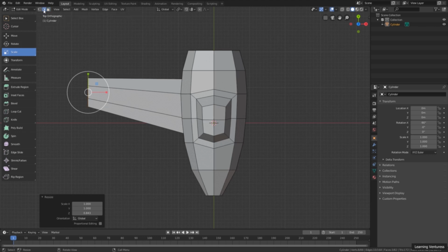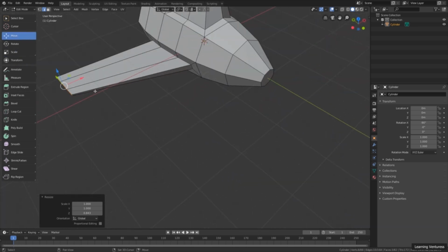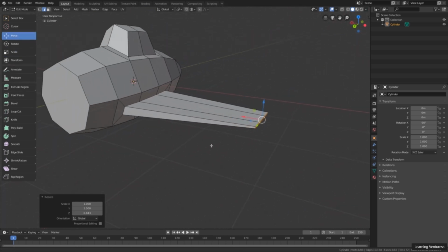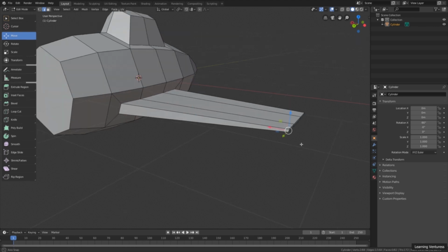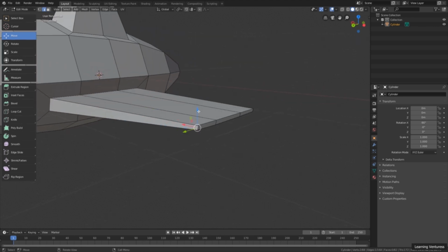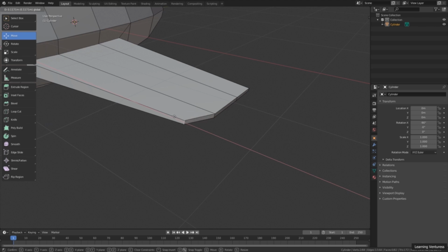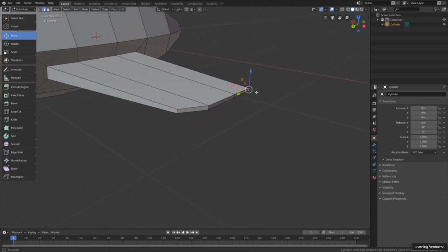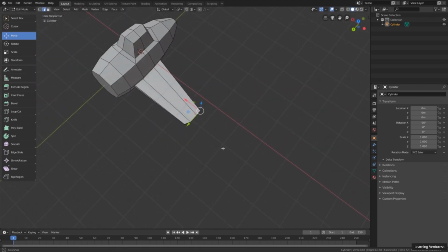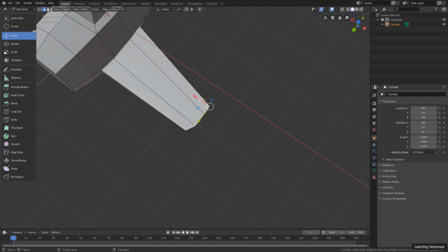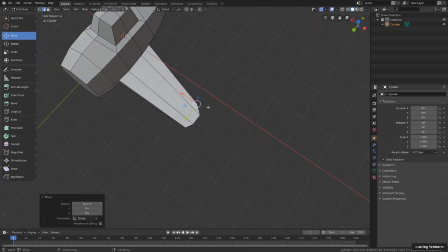So I can activate the edge selection mode up here. I'm going to activate the Move tool, and I need to select only the edge of the corner of the wing and move it a bit to the center, so that we can start to have this round shape in the tips of the wing, like this.